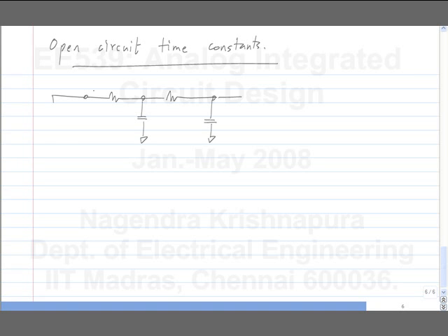So you disable the input, okay, and let's say you have a number of capacitors. In this case I will take 2. So you first take one capacitor. When you are dealing with a particular capacitor, you open circuit every other capacitor. Okay. So this is the circuit we have. And you look at the resistance that appears across the capacitor.